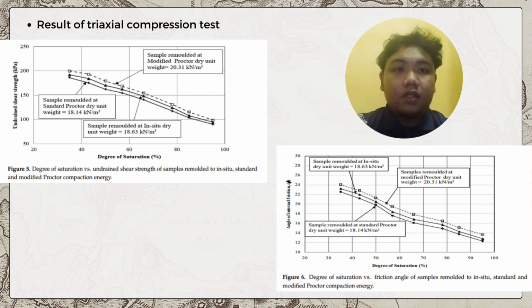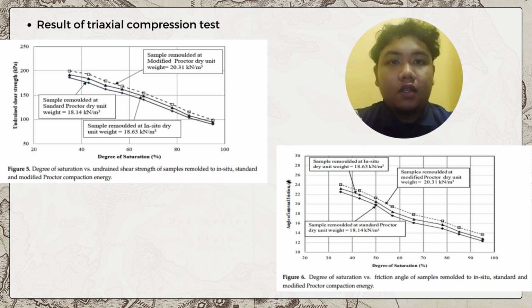According to the slope stability study conducted in GeoStudio, the landslide along the Jika Gali road was caused by a reduction in the shear strength of the slide material due to a rise in saturation level. Consequently, with the increase in saturation level, the effective normal stress decreased along the slip surface. Stability analysis of the landslide shows that the factor of safety reduced as the saturation increased from 35% to 95%. When the saturation was about 85% to 95%, the slope was in a critical condition because of the low factor of safety.